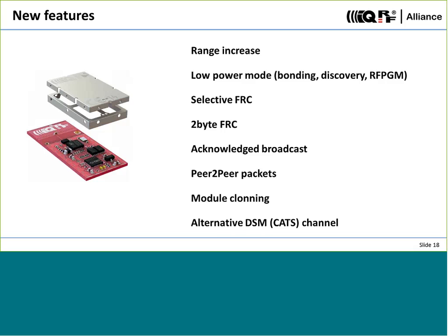Still using the example of street lighting, you can come to the light, and if there's something wrong with the communication on the light, you can get connected from your laptop directly to the line. You can then upload a new firmware, even your operating system, and do a lot of servicing things.